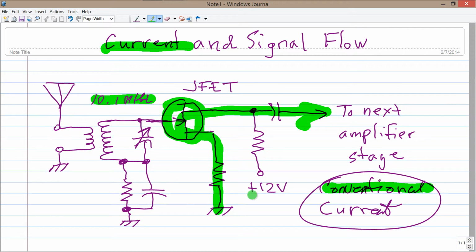So we're talking here about tracing the flow of a signal through this amplifier. It goes in weak here and comes out stronger here, maybe 10 times as strong. And the reason it does is because this device is specifically designed so that small changes in this voltage between the gate and the source produce large changes in the current from the battery that flows through this junction field effect transistor. If you need more information about this and related topics, I recommend a complete electronics course.